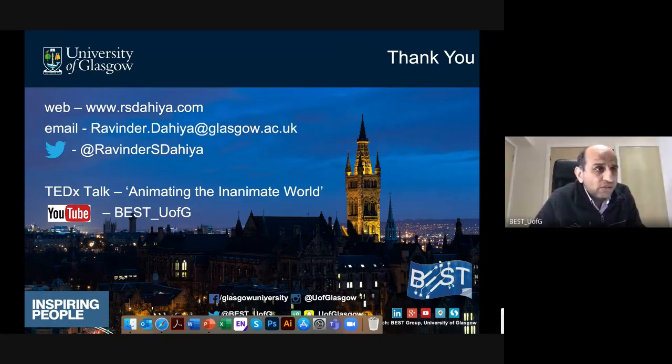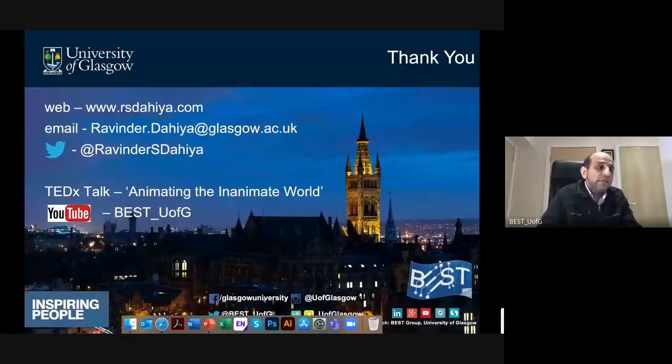There's a question, okay, sensors can be used in many different fields. I have a question regarding suitability of material in harsh environments. Devices were sandwiched between polyimide; how can the device behave at high temperature, and durability? It's a good question because there are several applications where electronic skin can be used and harsh environments would be needed. My answer here would be polyimide is not the suitable material, particularly if the harsh environment has high temperature. Polyimide among various flexible materials is the best because it can withstand up to 400 degrees. Others would melt at 150 to 200. So that way polyimide is slightly better.